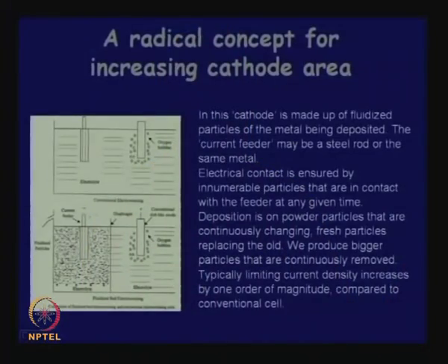Now, coming back to this question of fluidized bed electrolysis, in theory it can produce 10 times as much in the same cell, but there are technological problems. The problem of handling large volumes, you need pumps which will continuously pump things, the pumps may fail, you need more plumbing. If you have seen a fluidized bed setup, there are some very interesting requirements of fluidization they have to satisfy. Anyway, let us move ahead.